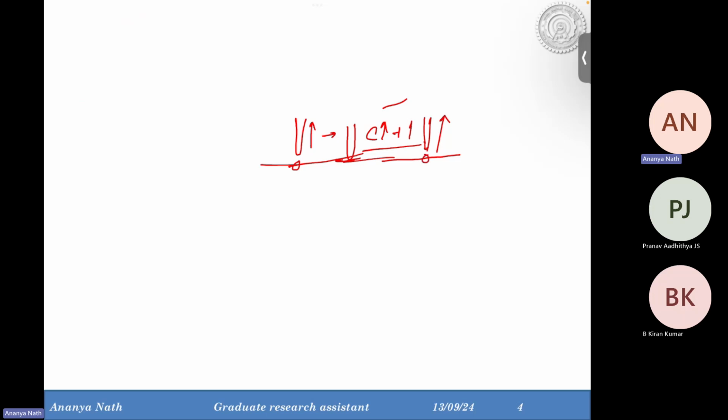So this is how it works. It works on the principle of short circuiting and retracting the wire from the melt pool. And as you are not establishing a constant current or providing a laser or anything, you call it cold metal transfer, but it is not cold.